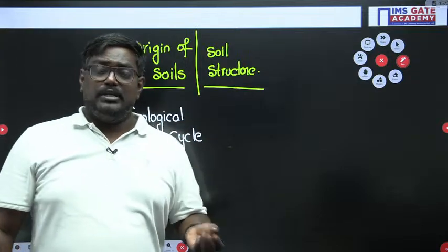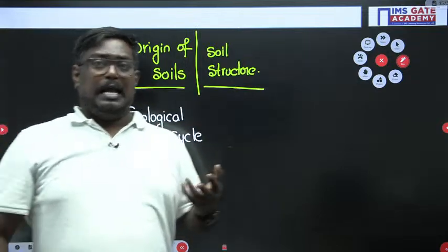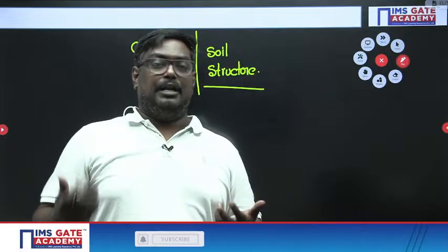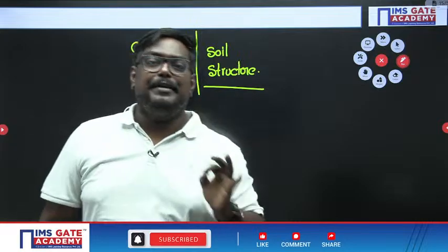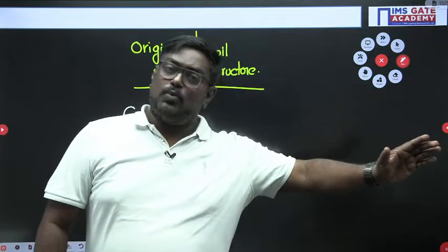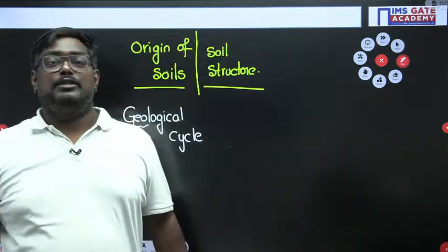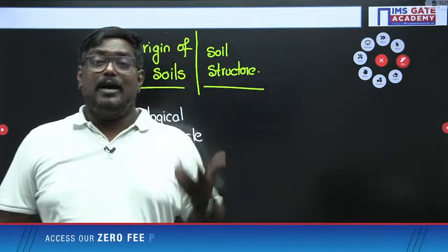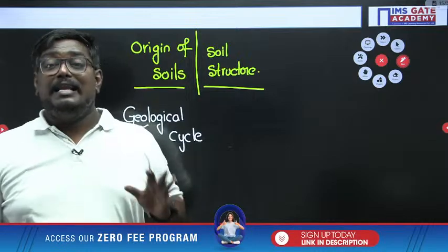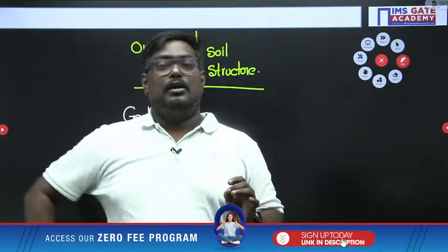Now my dear students, we have again two types of soils. Actually there is no name like this, but still, transported soil and non-transported. Transported means sedimentary soils: soil particles created at one location and finally deposited at another location. When I talk about residual soils, soils which remain on the parent rock without any transportation are the residual soils.